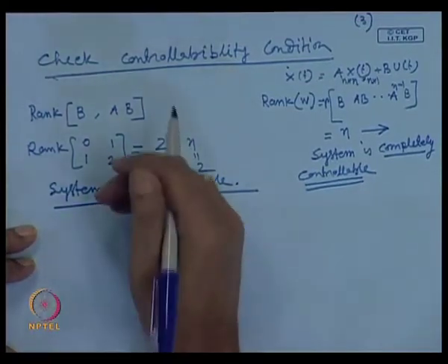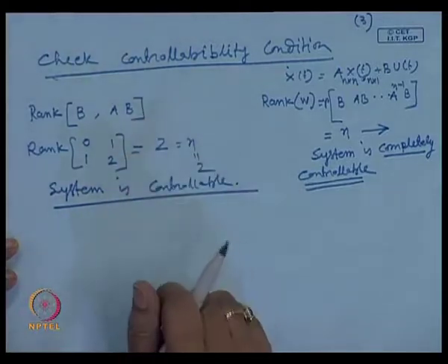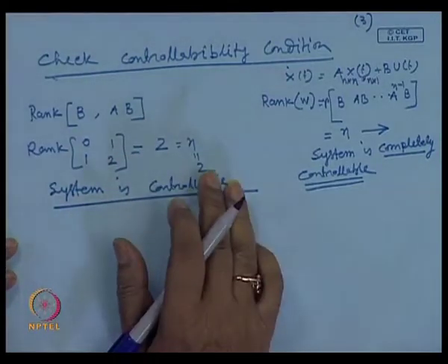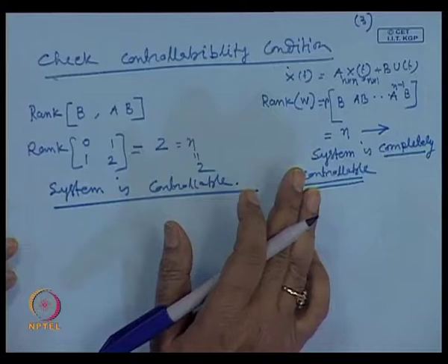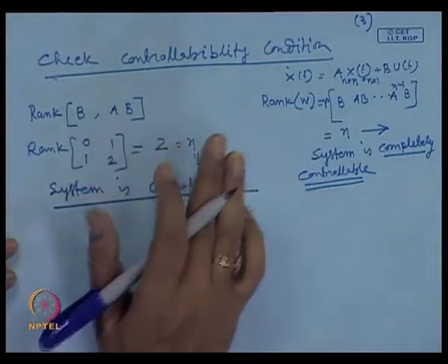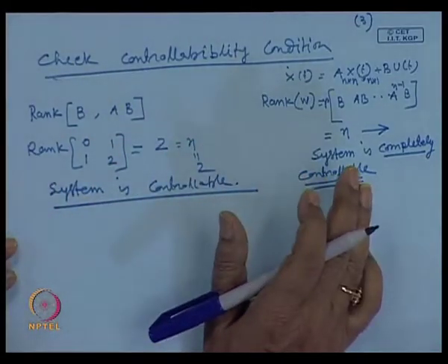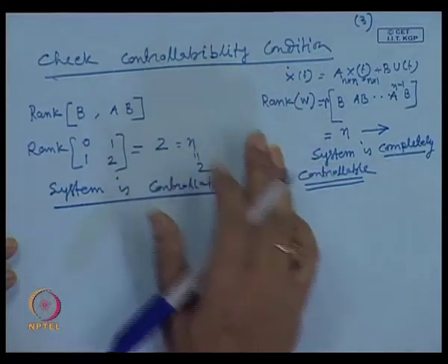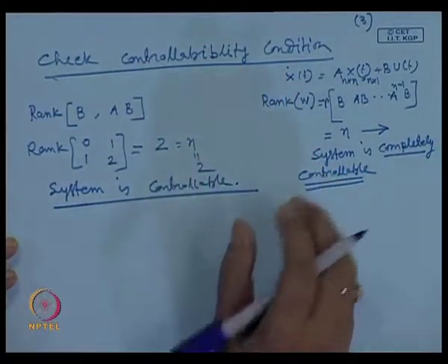So, this then we can proceed. If the system is not controllable, or at least not stabilizable, then you have to check whether the system is stabilizable or not. Stabilizable means, if you have an open loop system with an unstable mode, that unstable mode should be stabilizable, in the sense you will be able to drive the unstable poles or the eigenvalues from the right half of the S plane to the left half of the S plane.